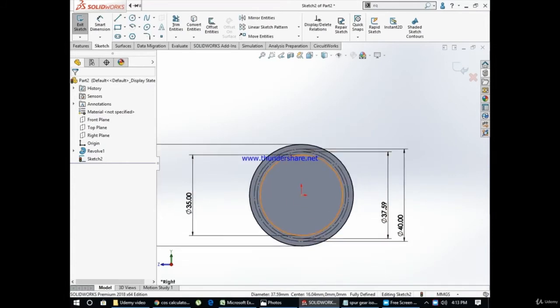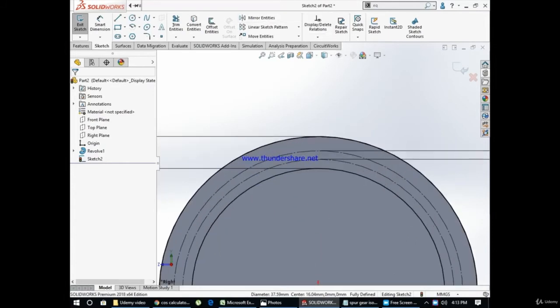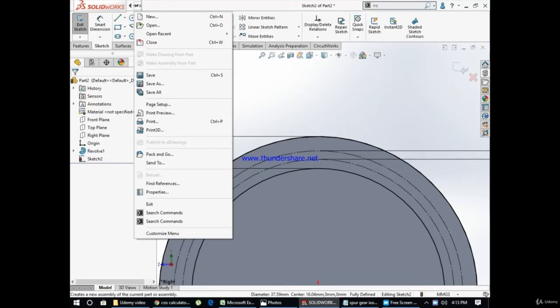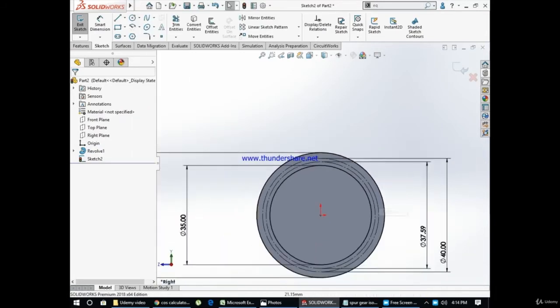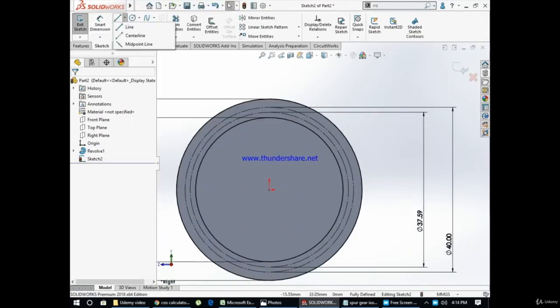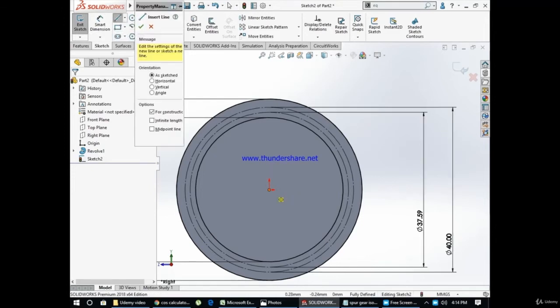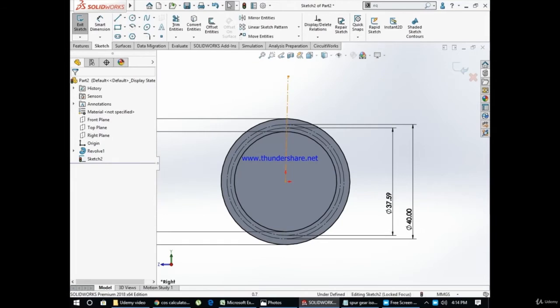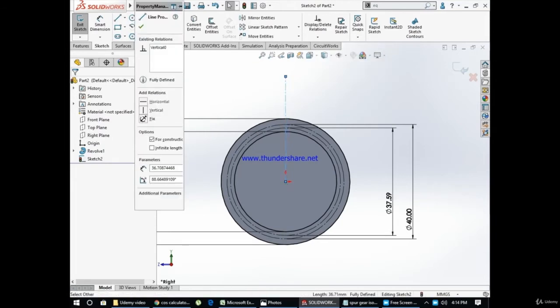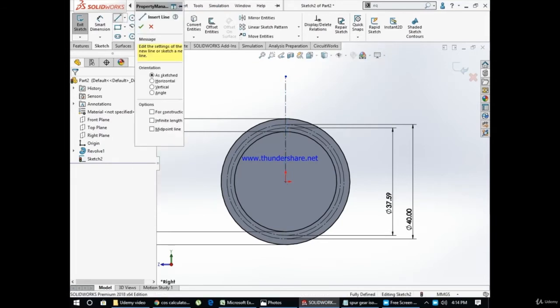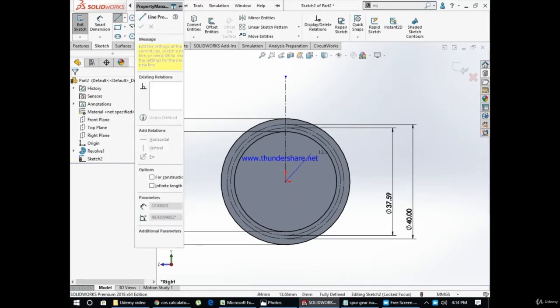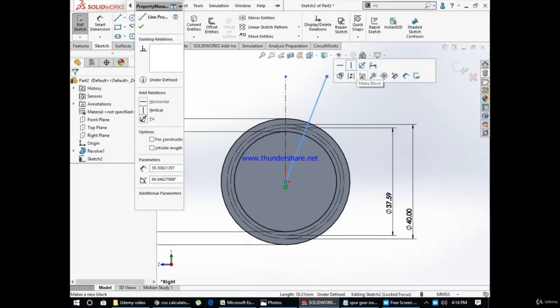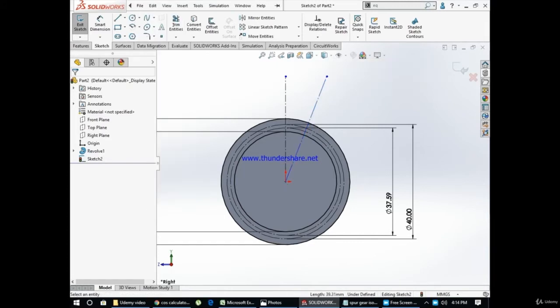Now after that, make flank radius. So to make here, just follow these steps carefully. And this is a very important one. Now whatever lines I'm taking, take all those lines as center lines so that you don't get confused. So take a straight line, vertical straight line, and take another line which is inclined. Dimensions of those lines don't matter.